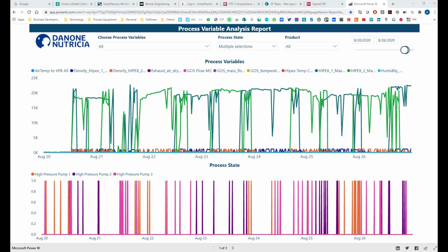But if you have somebody there who's familiar with PLCs and knows how to put in a PLC address and play with Kepware, then you can easily add your own tags into the historian. And in fact, that's where we'd like you to be as a customer, to be able to manage your own data in and out of the historian without us having to be involved, and we'll give you whatever is needed to be able to do that yourselves.